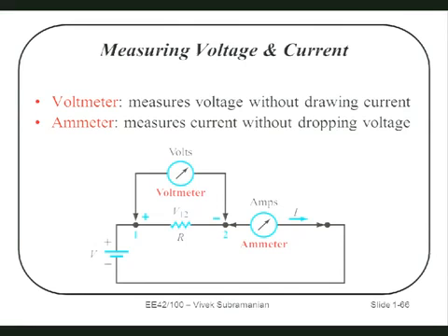In practice, we do not get ammeters with 0 resistance. A cheap multimeter, in fact, the ammeter is worse than the voltmeter. The voltmeters are pretty good. 10 megohms, in some cases actually teraohm. So very high numbers, or gigohm. But cheap ammeters will typically have a resistance of 0.1 ohms. So that's not that low. It's enough that it actually does perturb circuits with very low resistance.